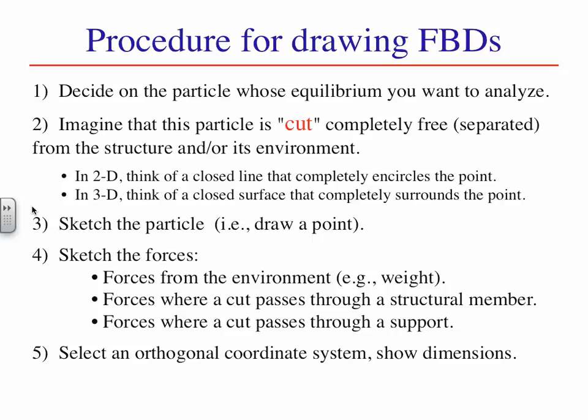First, we'll decide on a particle to isolate. Sometimes this is obvious. In other instances, and in examples to be seen shortly, the particle is a joint between intersecting structural members. In such cases, equilibrium of the joint imposes a relationship between the forces of the structural members intersecting at the joint. In complicated assemblies, points of intersection of interacting members are often of interest.